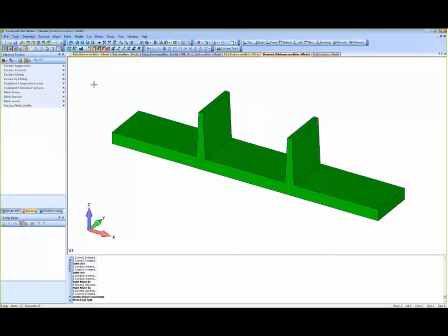They've also added some really cool automatic options for editing the thickness of your mid-surfaces if you're using shell or plate elements. This comes in handy when you have maybe a composite layup where you have a lot of shells on the same plane, but those shells need to have different thicknesses. In one of the newer NX Nastran releases, they've added the option to update the thickness of specific elements right on the element card, on the CQUAD4 or the CQUAD8.